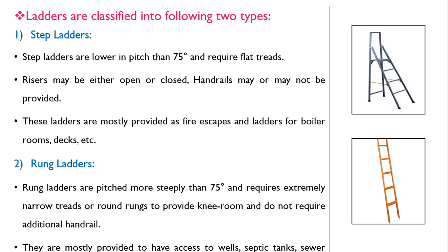Now coming to different types of ladders. Step ladders are there, rung ladders are there. This is a step ladder. Step ladders are lower in pitch than 75 degree and require flat treads similar to stairs. Risers may be either open or closed. Handrails may or may not be provided in case of a step ladder. These ladders are mostly provided as fire escapes and ladders for boiler rooms, decks, etc.